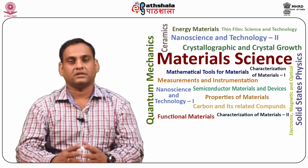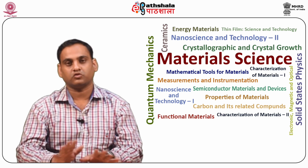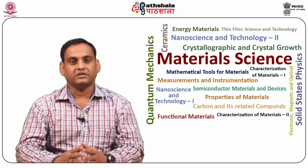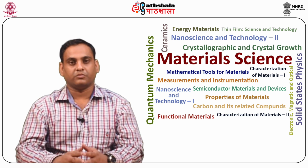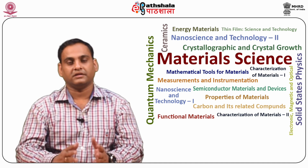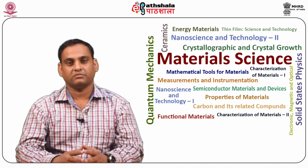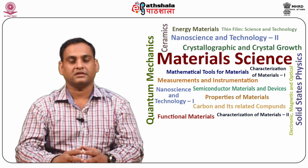Nickel-iron alloys. These alloys, known as permalloy, are extremely versatile and are used over a wide range of compositions, from 30 to 80 weight% of nickel. Over this composition range, the properties vary and the optimum composition must be selected for a particular application. The high nickel content alloys have high permeability. Around 50 weight% nickel have high saturation magnetization, and low nickel content have a high electrical resistance.